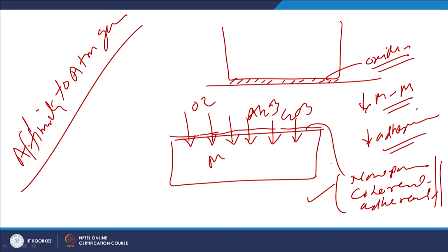On the other hand, in the case of iron oxide, the metal oxides are porous, and they are not coherent and not adherent. So, they will get removed easily. This removal of such oxides leads to the exposure of fresh metal surface for further interaction with the atmospheric gases, which in turn will further promote the wear of the material due to interaction with the ambient conditions.